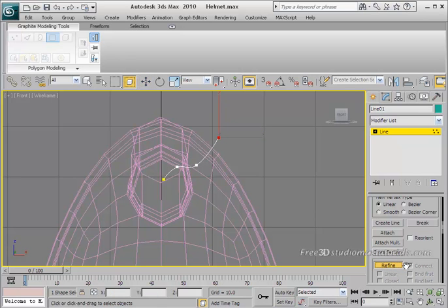so you can also add a vertex by clicking on this refine, and with the connect checkbox selected, click anywhere where you want a vertex. Just click back on refine to come out of the refine command. Okay, set it to something like that. Select this upper one, bring it down and bring it inward to the x-axis. Okay, now click on this line tool to deselect the line option.